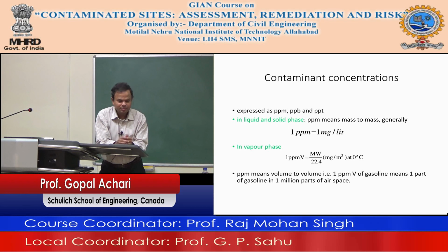For example, if you're taking out the vapor and treating the vapor, the contaminants present in the liquid phase or in the solid adsorbed phase will start to move to the vapor phase, and now you will have a much higher volume than if you had just considered the vapor phase. The cost of the project will be significantly higher if you factor all that in as compared to if you don't factor it in, and that might be a problem for you.